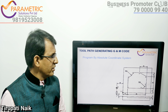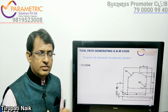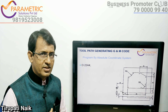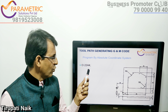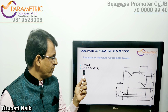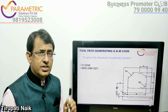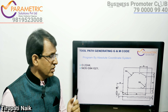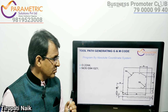Okay. So the first step is, the program always starts with O and 4 digits. Here I have taken the program number as O2244. The second block is N05, then G94, which is feed per minute. Then G21 is metric units.